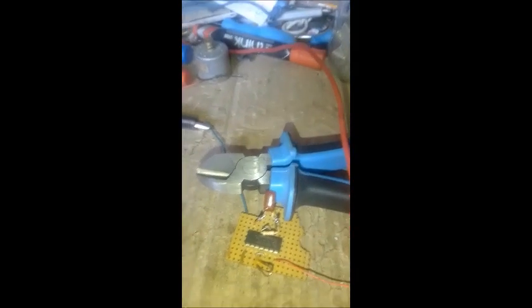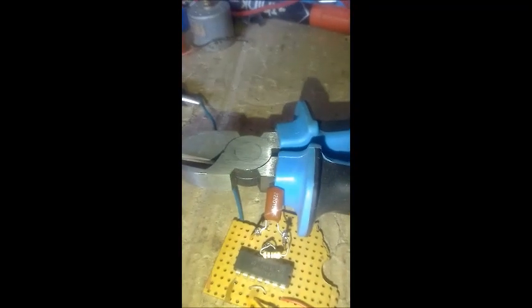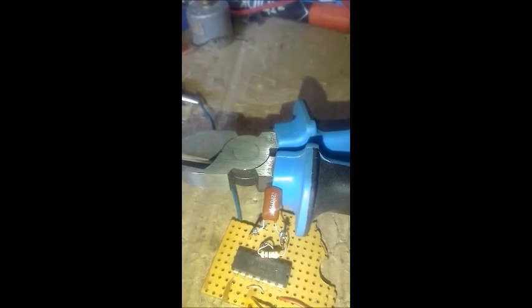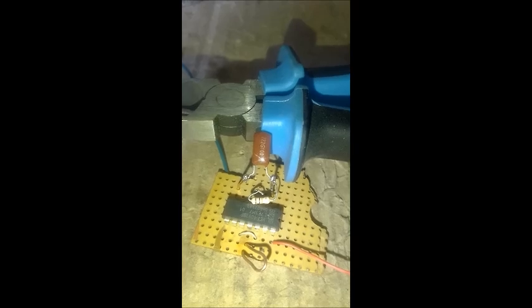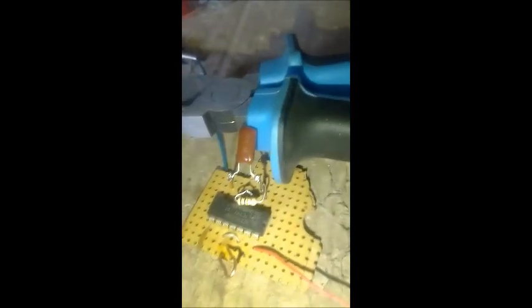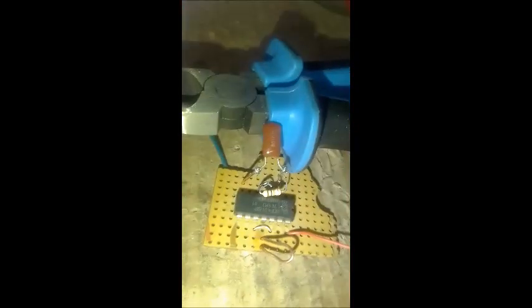Right, so I'll demonstrate first with a capacitor. This should be a Mylar or polypropylene capacitor, and its value is 2.2 nanofarads, and that's a 4093 IC there, which is a 4 NAND gates IC. The resistor is a 10 kilo ohm resistor, only that here you can see the color. So we have a 2.2 nanofarads capacitor and a 10 kilo ohm resistor there.